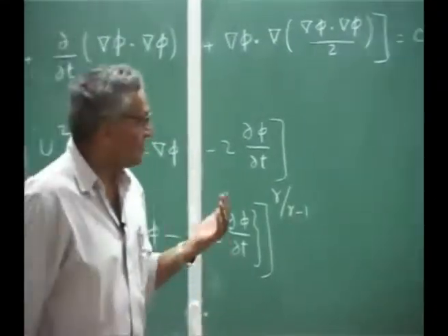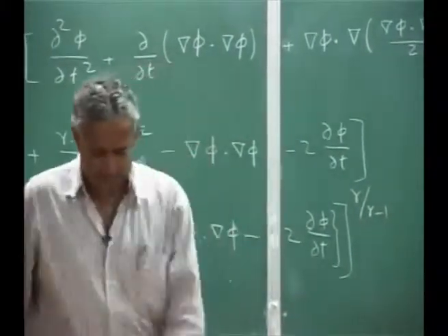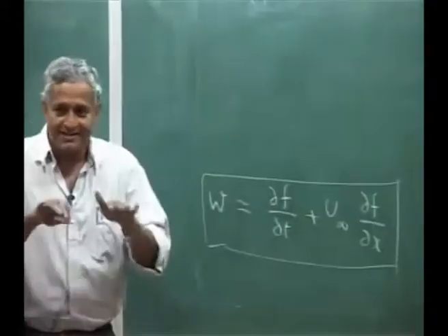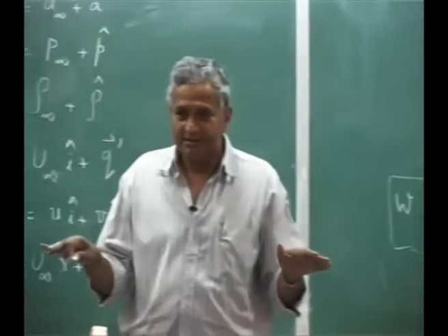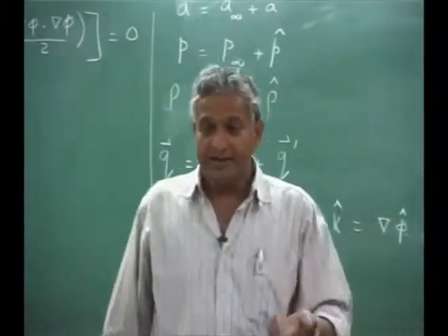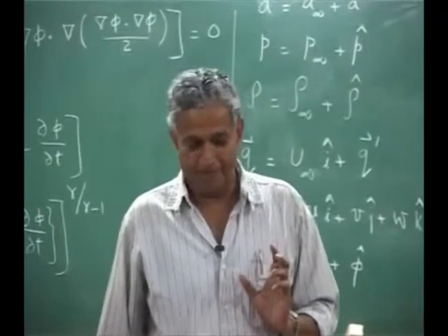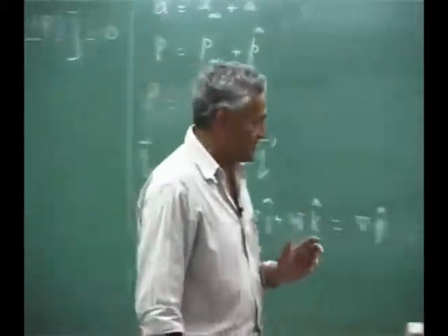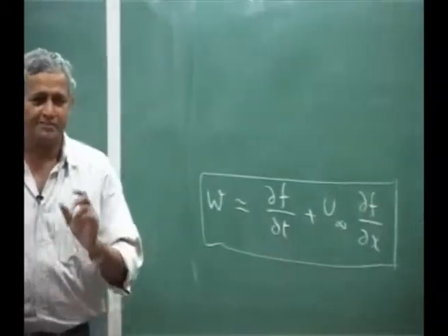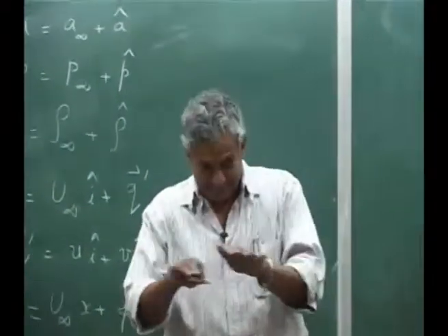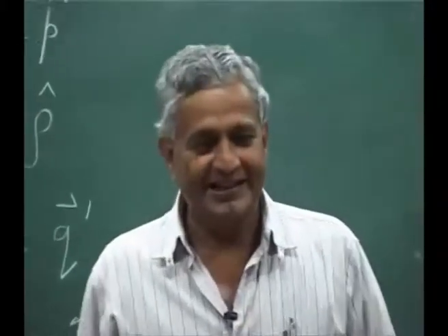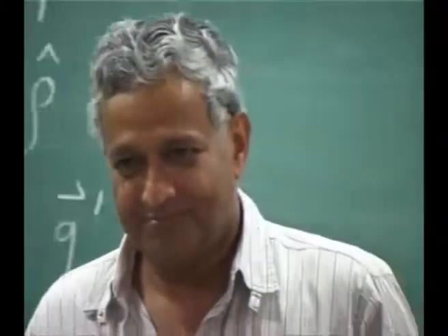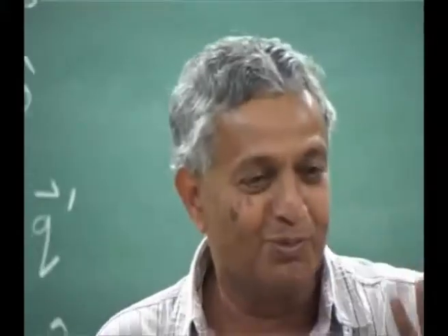Now why I am saying from the boundary condition, you may ask the question. See, I am saying the disturbances, because this boundary condition is only near the surface of the wing. If I can make an assumption that my UVW, that is the perturbational velocities, are small near the surface, the boundary, then I can make an assumption that far away from that they can be small.